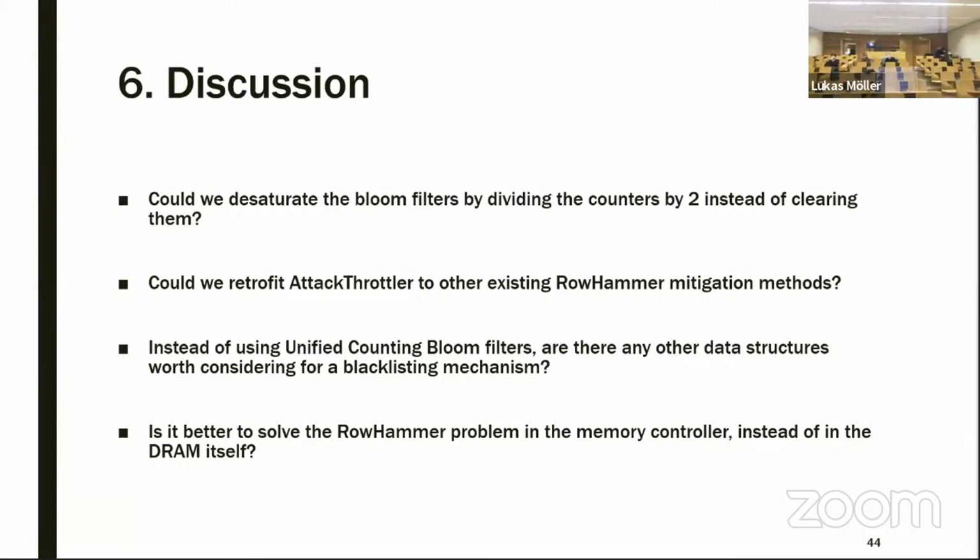No, I'm not disputing the foolproofness of the defense, but what I'm saying is that I guess a more useful context would be that RowHammer is a read disturbance error, and read disturbance errors are not exclusive to DRAM.